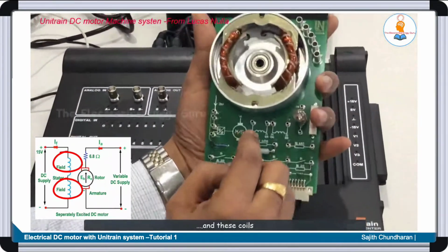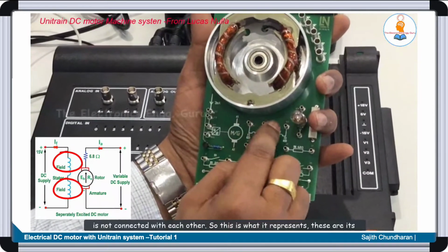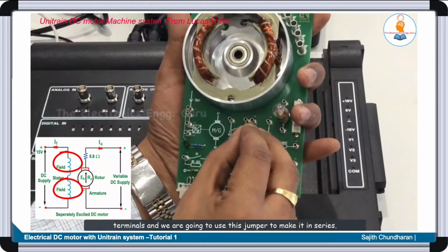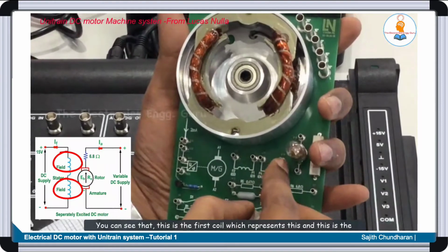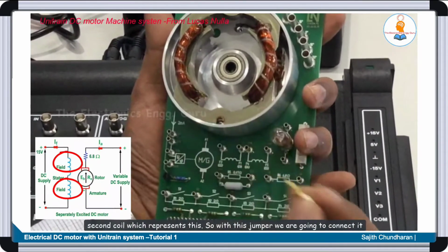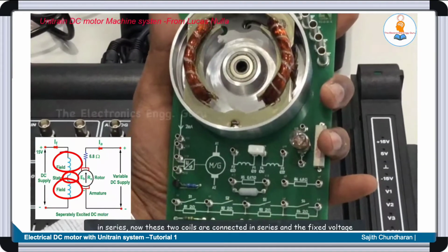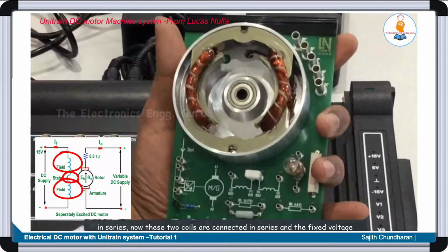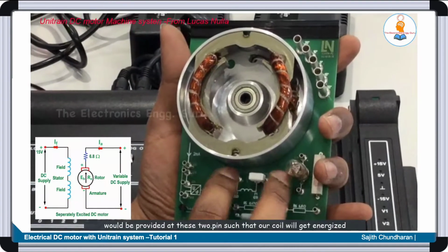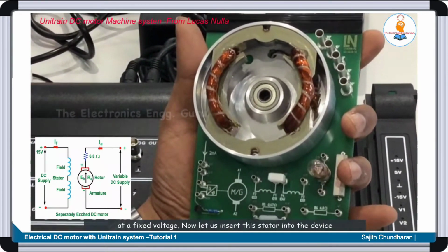And these coils are not connected with each other. So this is what it represents. These are its terminals, and we are going to use this jumper to make it in series. You can see that this is the first coil which represents this, and this is the second coil which represents this. So with this jumper we are going to connect it in series. Now these two coils are connected in series, and the fixed voltage would be provided at these two pins such that our coil will get energized at a fixed voltage.